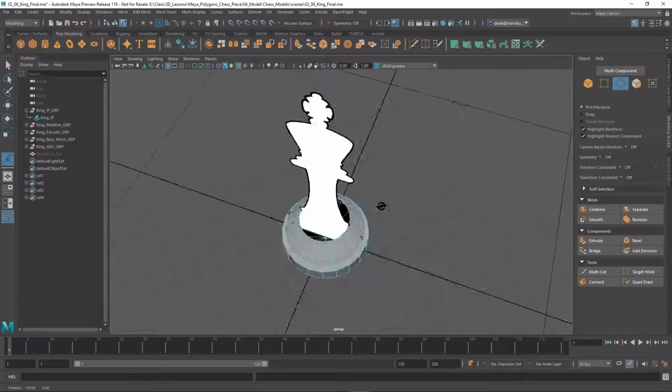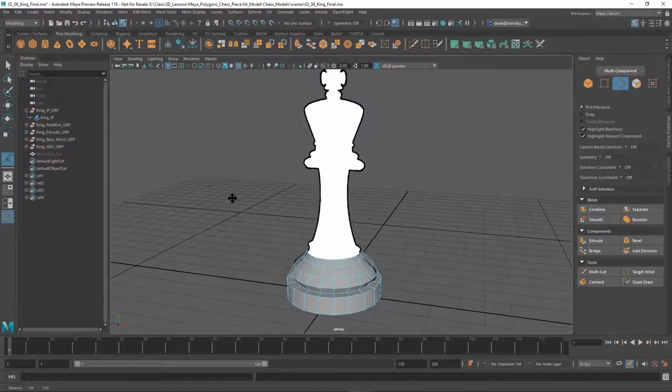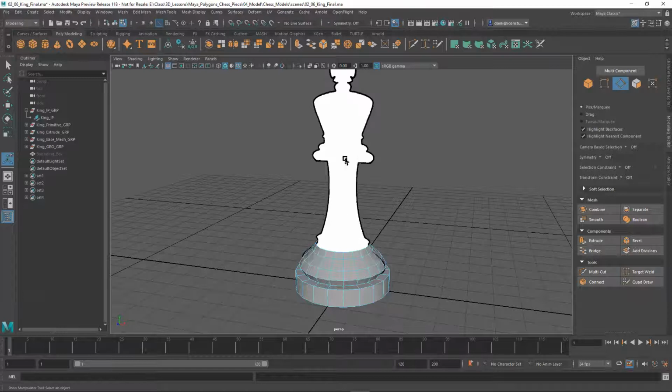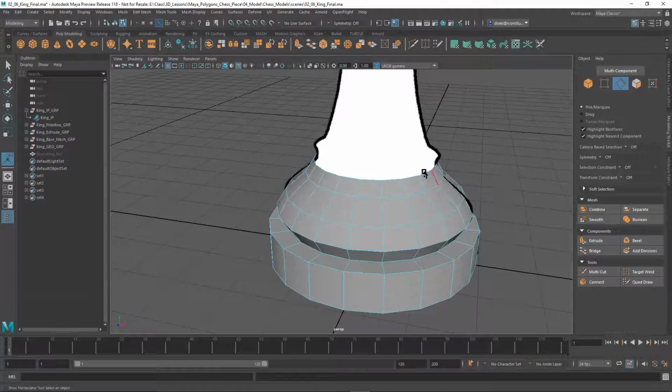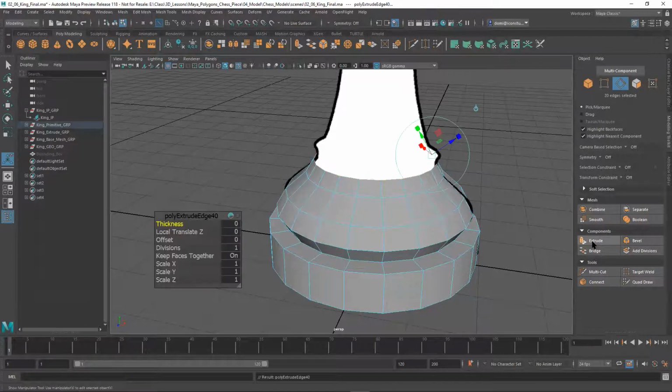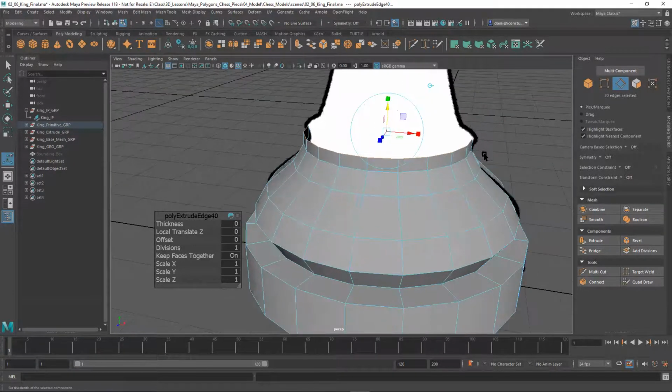Okay, so let me get to, well, I'll continue up through here, and then I'll just show you how it goes, okay? All right, so now we're going to double click on this again. We're going to hit extrude, click on this, so we get to the global axis, the world axis. Actually, hold on, you know what I want to do? I want to bring it up. Yeah, I'm going to try and get this little lip here, okay? So I'm going to do the scale.